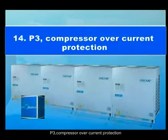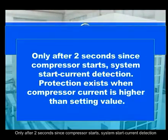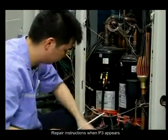E3. Compressor overcurrent protection. Only after 2 seconds since the compressor starts does the system start current detection. Protection exists when the compressor current is higher than the setting value. Repair instructions when E3 appears.